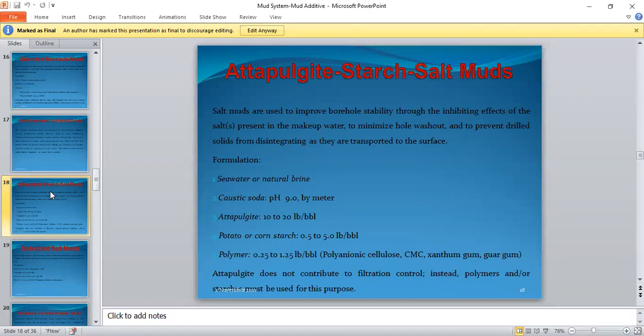In some areas the hole is more than 16 inches in diameter. Some areas it could be 16.5, some 17, 18, it can go as bad as 19. That's what we mean by washout. Washout is the area that you did not drill, but has become part of the hole diameter.